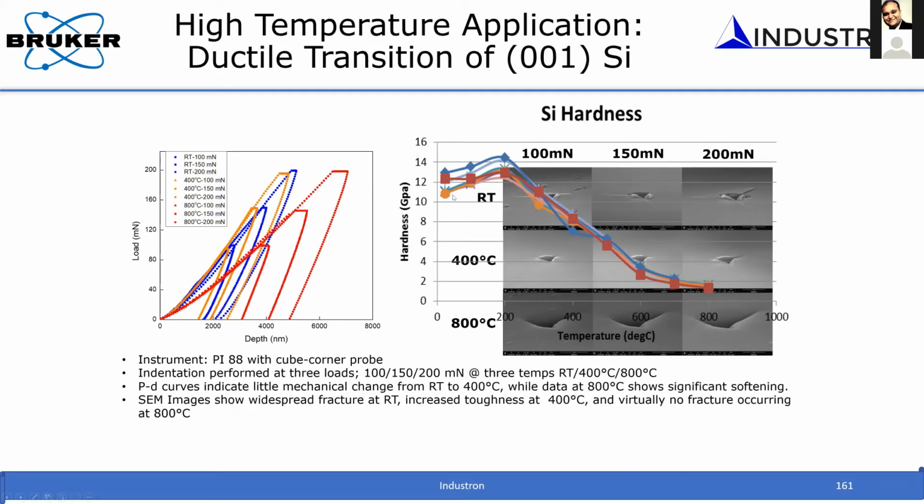But in this case, a hardness increase means a decrease in plasticity, and then there is an increase in plasticity. The reason is the two competing mechanisms that I talked about: from room temperature up to a certain temperature, the phase transformation is the dominant mechanism, and above a certain temperature, the dislocation-based plasticity becomes more dominant. Okay, that's why you have this.